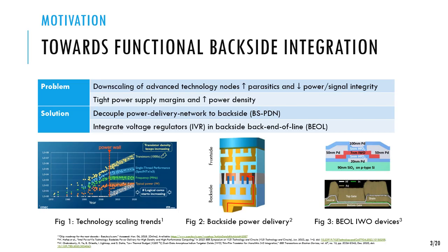However, despite these advantages, a standalone BSPDN does not fully solve all power-related challenges, due to the fact that one key issue is underutilization of the backside, as backside metal layers are primarily dedicated to power routing. Additionally, voltage noise from off-chip components will not be accounted for as much with on-chip backside power delivery networks. So we have to think a little bit more out of the box about how we can tackle off-chip parasitics and off-chip IR drop as well.